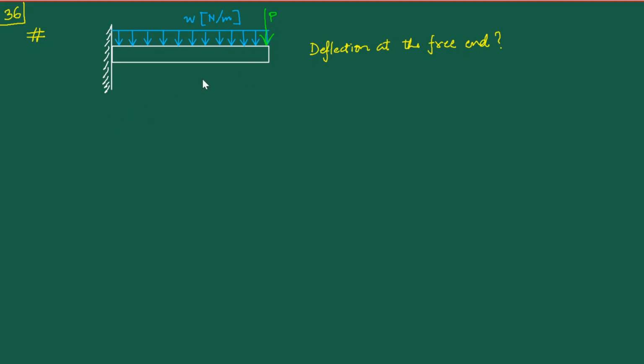So to introduce a fictitious point force at the free end, and proceed as usual, what we'll do is take a cut section at a certain distance from this free end, and we'll take our origin here at this free end and take the x-axis oriented like this.